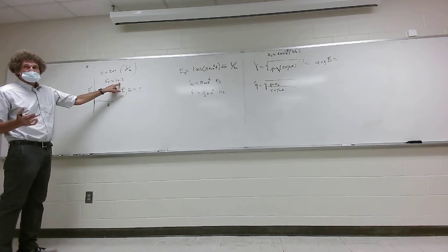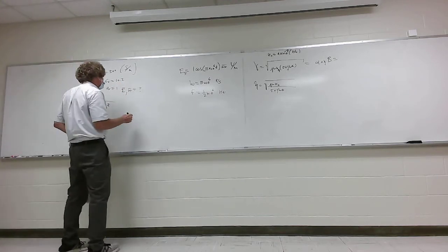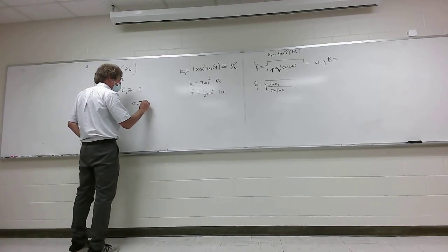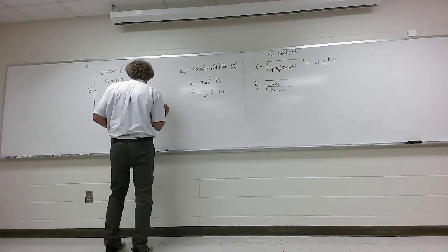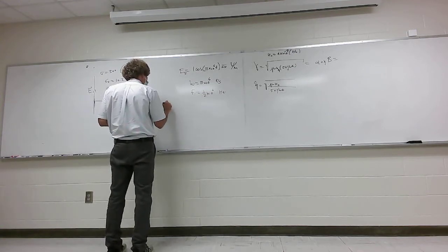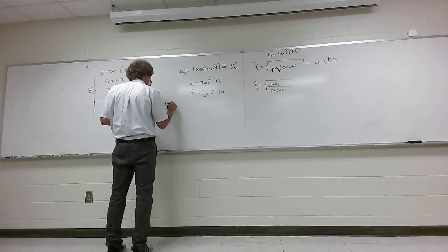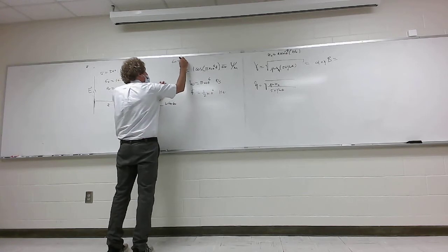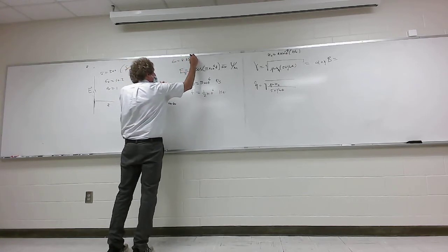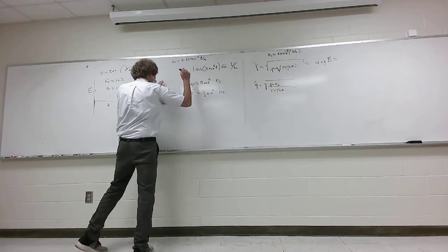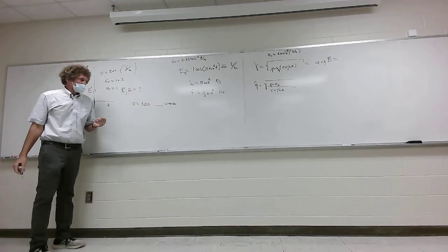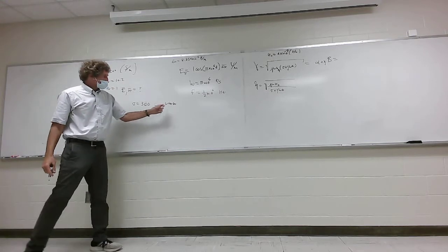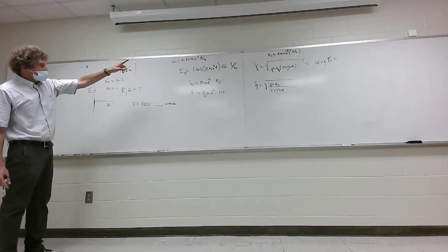You don't have to do this, but they'll take sigma as 300 and compare that to omega epsilon relative times epsilon naught, where epsilon naught is about 8.854 times 10 to the minus 12 farads per meter. So they're comparing these two. We have 300, omega as pi times 10 to the 6, epsilon relative 10.2, and epsilon naught.